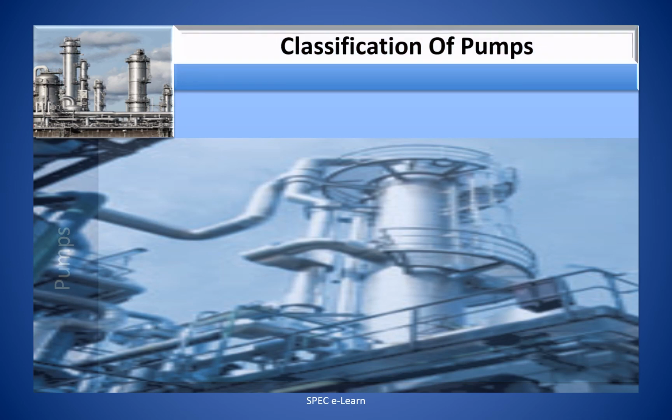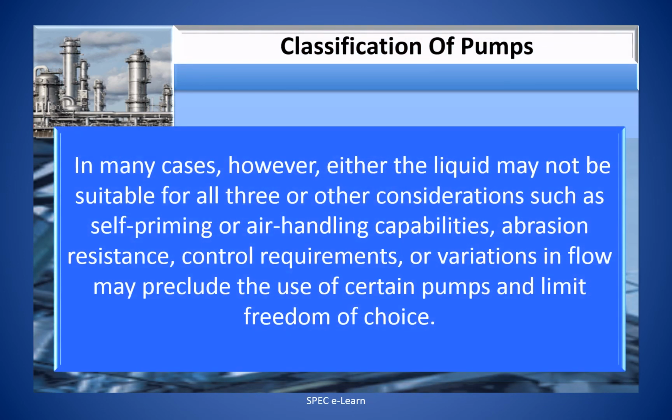In many cases, however, either the liquid may not be suitable for all three, or other considerations such as self-priming or air handling capabilities, abrasion resistance, control requirements or variation in flow may preclude the use of certain pumps and limit the freedom of choice.